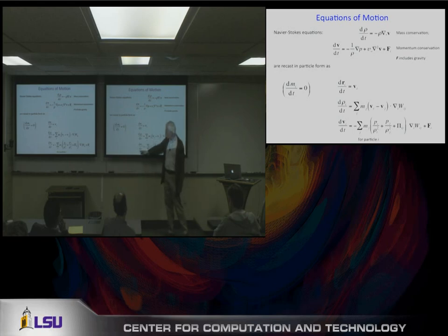And then the acceleration of each particle will depend on pressure, which looks a little bit different than in this form, but you have to trust me that this comes out of the math. So this is the pressure gradient term. This might be the viscous term, but again, it's analytical gradient here. So that part's pretty nice. So for each particle, we've got an equation. We have to solve these three equations, and the problem is solved.